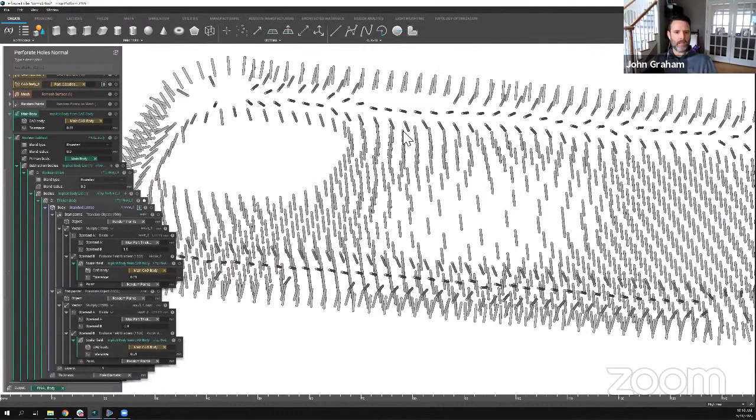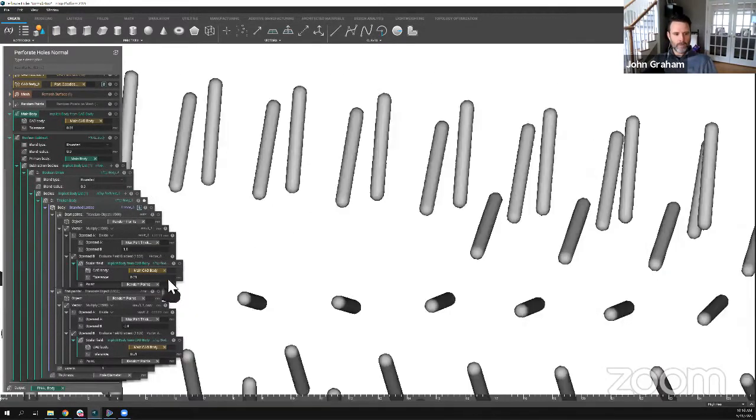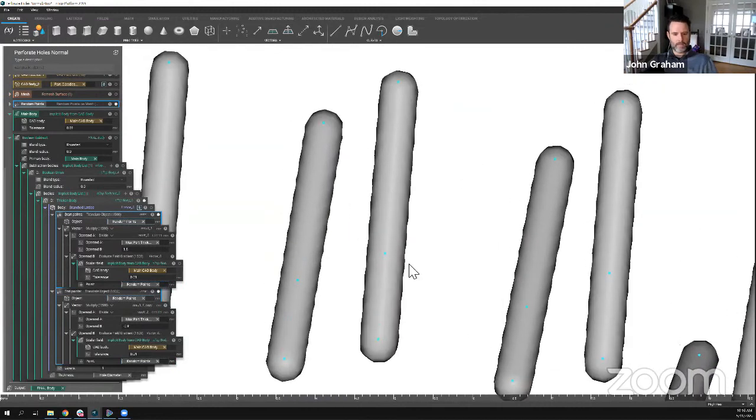How did I do this? How did I create all those posts? Well, I created a series of points all over. Let me zoom in on these points and you'll see what's going on. Let me explain this in more detail. This point right here is the exact inside surface of the mold, or the outside surface of your phone, right? Well, all I did was create a copy of those points going in one direction and a copy going in the other. And these are at different distances. I intentionally set that up. It's just a function over here of the maximum thickness that I entered. So you see I've got some values of -0.9 and 1.8, and that's dictating how far apart those points are going to go.